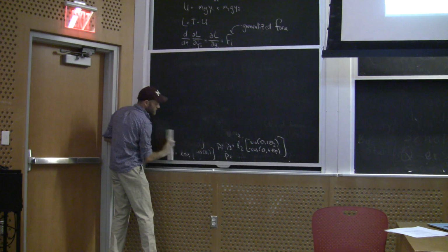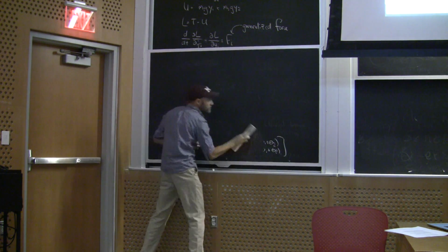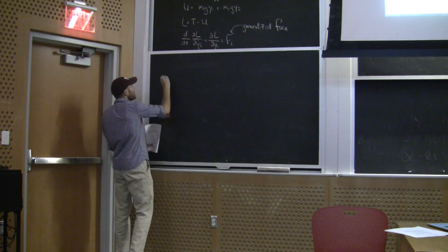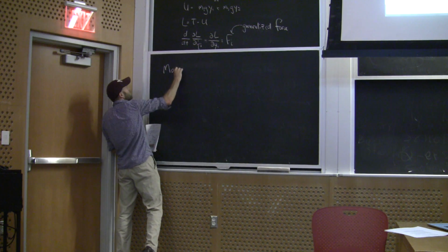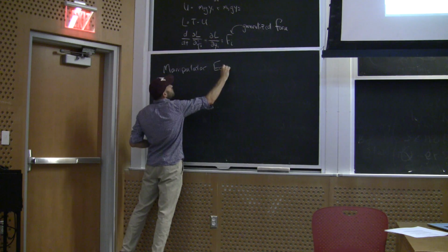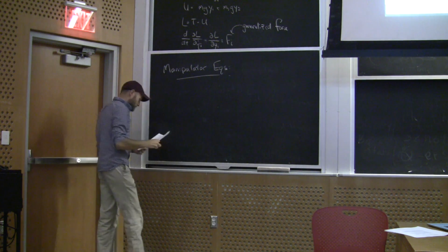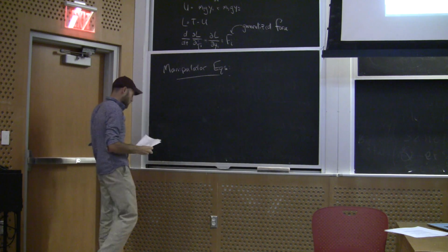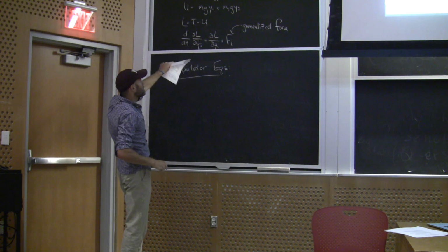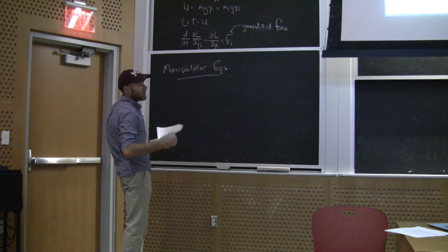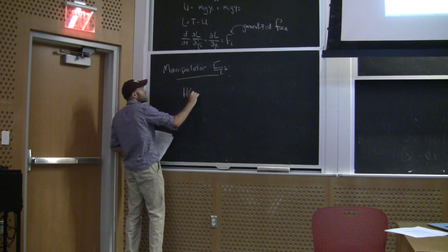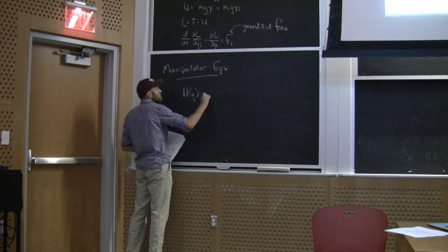And there's even more structure in the equations. It's not just control affine. They all subscribe to the famous manipulator equations, okay? It turns out that if I go through this process for my robot, whether it's the cheetah robot or a double pendulum, I'll come out with something that takes this special form.